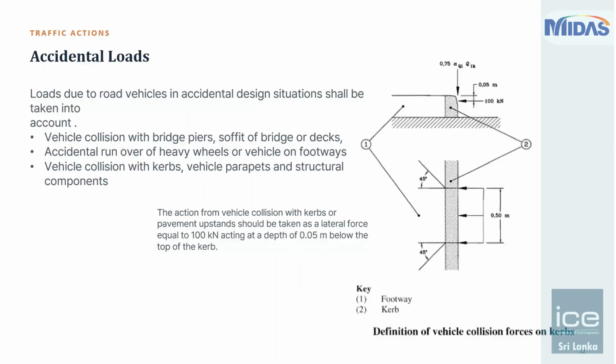Also, sometimes when we model the crash barriers, they have handrails, right? So this is about the local design, not the global design. Handrails often see the live load, not just vertical live load, but they have to be also designed for lateral live load. So the guardrail will see an out of plane moment arising from the live load, both vertical direction as well as the horizontal direction. Okay, so we must consider that for the design of the guardrail.